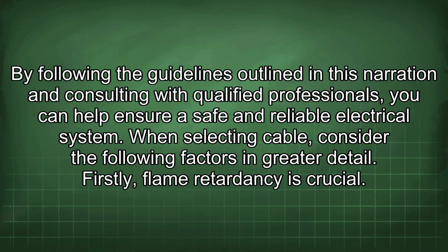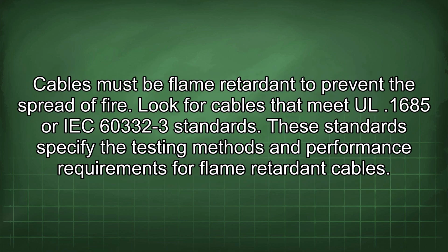Firstly, flame retardancy is crucial. Cables must be flame retardant to prevent the spread of fire. Look for cables that meet UL 1685 or IEC 60332-3 standards. These standards specify the testing methods and performance requirements for flame retardant cables.